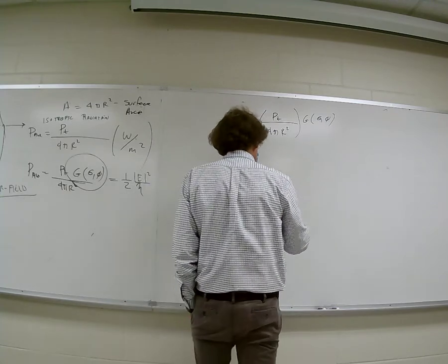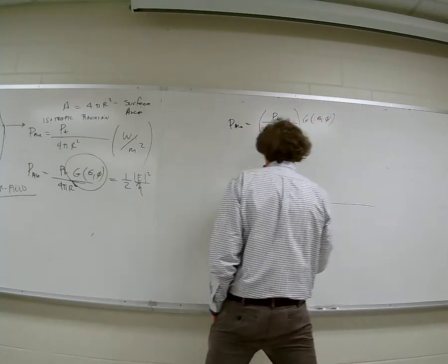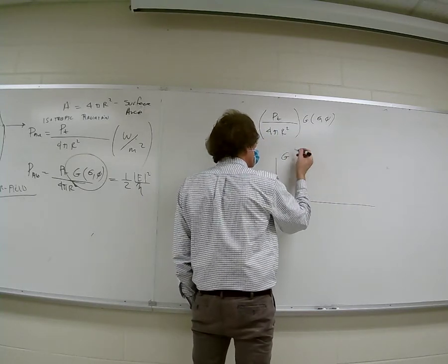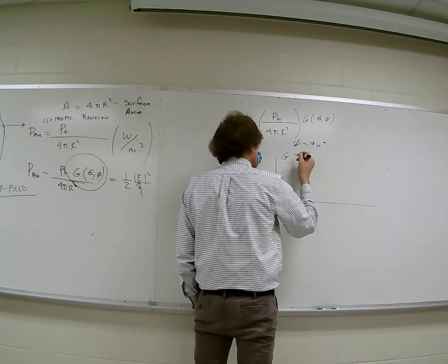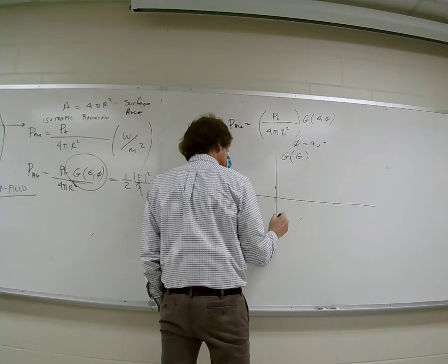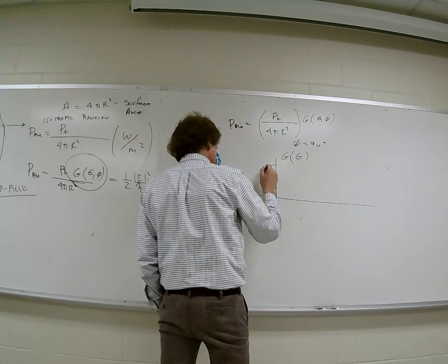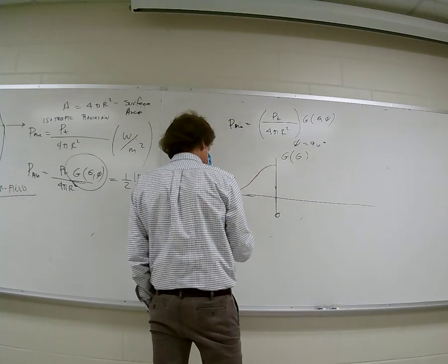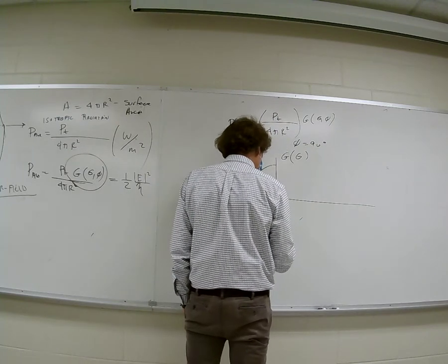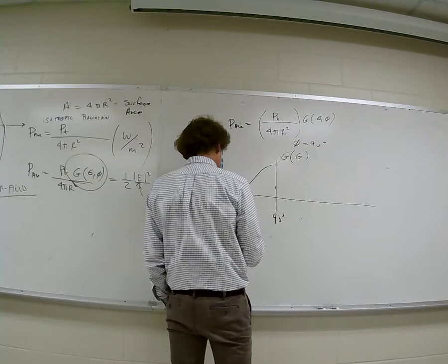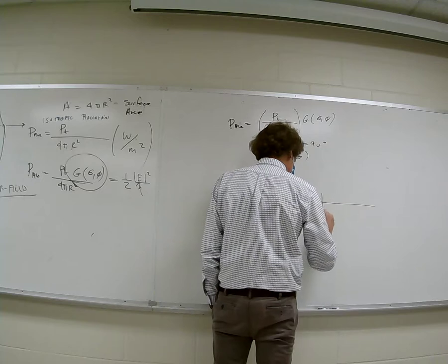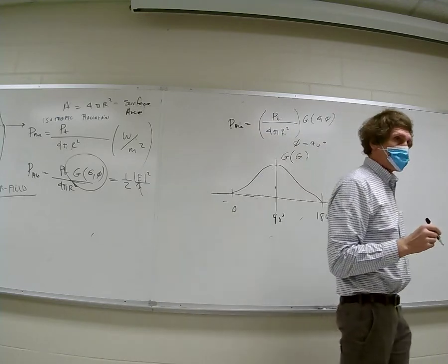So what's typically done is, this is called a cut. They'll take a look at the gain of an antenna, we're going to do it in linear, and they'll hold phi at 90 degrees, and they'll take a look at it versus theta. So the gain may do this. If this is 0, it may do this. Let me call this 90 degrees and explain this. And this would be 0, and this would be 180 degrees. Let me show you what I'm trying to do.